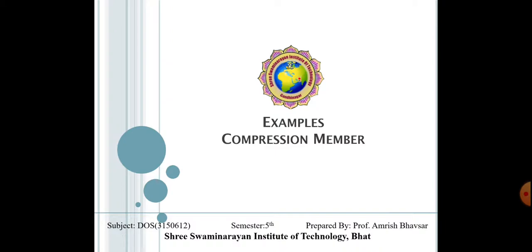So, for the designing or analysis of compression member, we have one important page of IS 800, that is page number 34. On that page, they have given us the design compressive load PD is equal to AE into FCD.